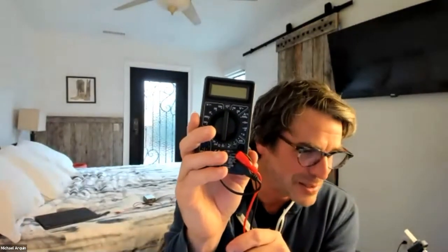In your kit, you've got a meter. It doesn't look exactly like this, but it looks somewhat similar to this. For these turbines, you're going to want to set it on DC voltage. And the range, this is not an auto ranging meter, so this is a meter that makes me set the range. Set it in the range of 0 to 20 DC volts. That's going to give you a nice range.